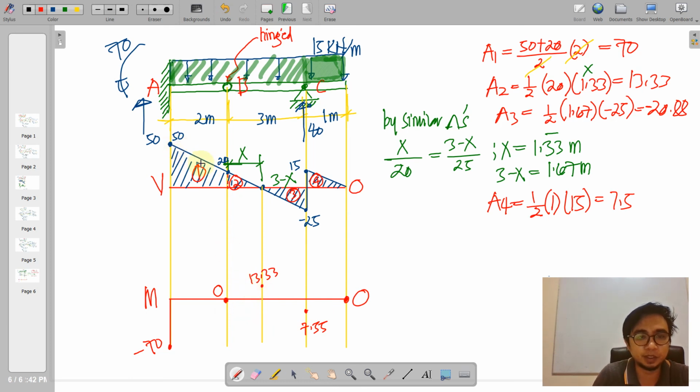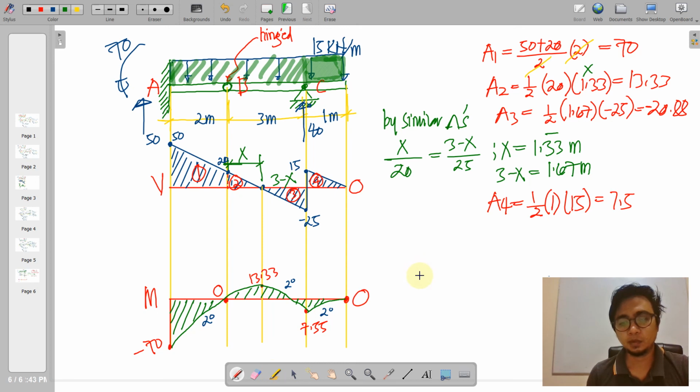From this one, this is a decreasing first degree curve. So when we have a decreasing, we have the direct relationship between shear and moment, that is concaving downwards. And basically this is our shear and moment diagram connected by this second degree curve. So this shall complete our moment diagram.